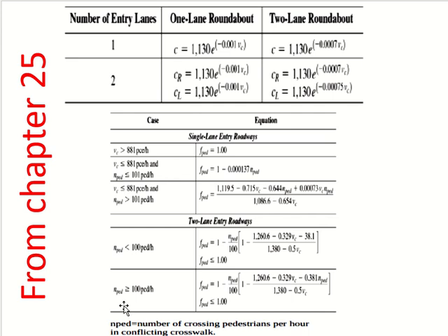If you have two lanes, you will use one of these two. Okay, so conditions. For example, look at the first condition. The first condition is your road has one lane. Your VC, what was VC? Volume on the roundabout. Okay. So if your VC is more than 881, then your adjustment factor is 1. So whatever capacity you have, multiplied by 1.